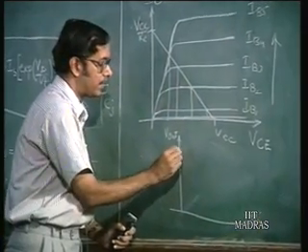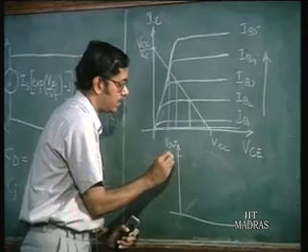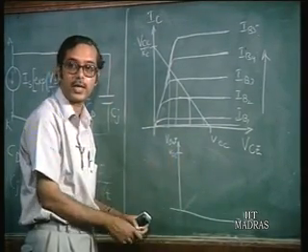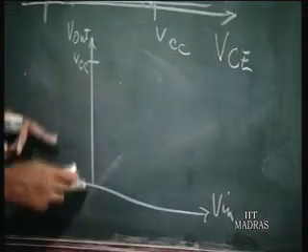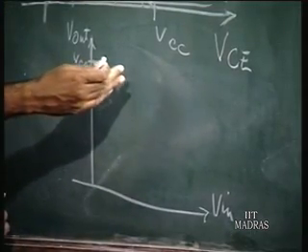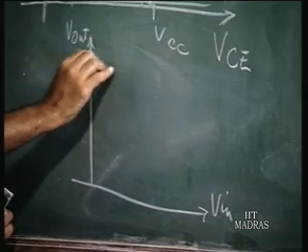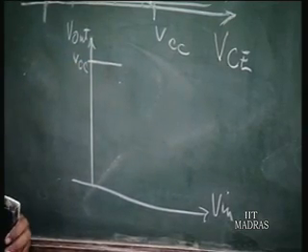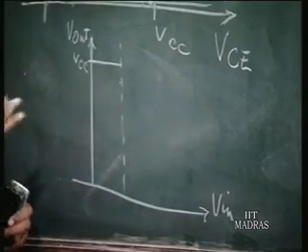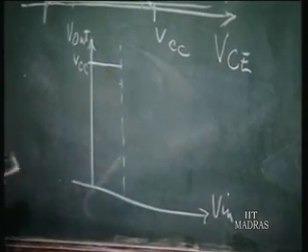Okay, so output voltage is equal to VCC when V in is 0. Now when you increase V in up to say 0.6 volts, it is the same. The output voltage is going to be equal to VCC. Now once you exceed 0.6 volts, what happens?